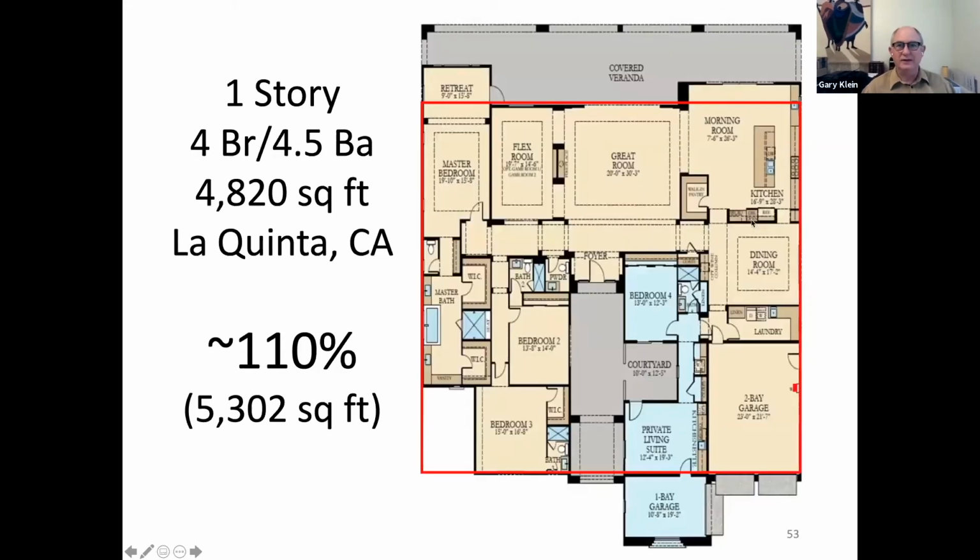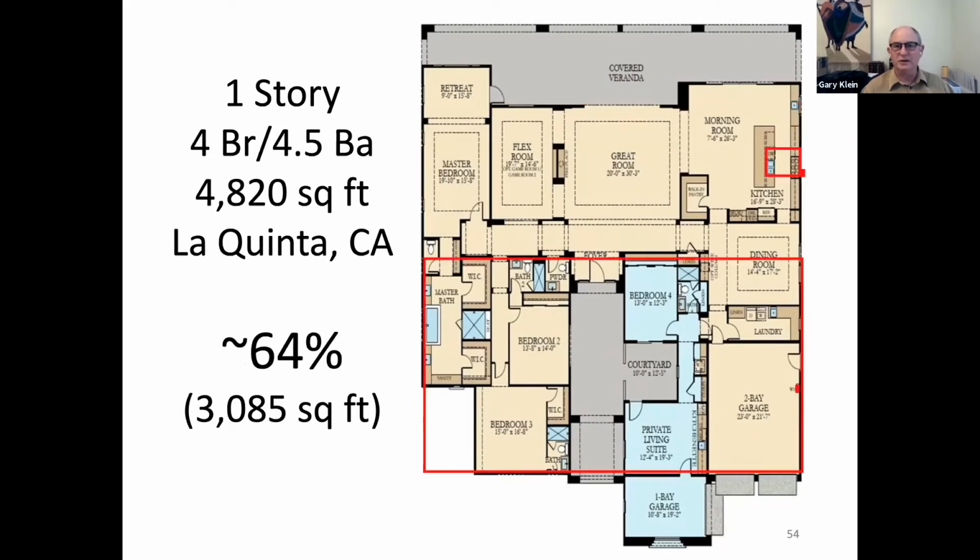How about this house? This one's, you know, a little pretty bad. It's got one water heater location in the garage. What if we split it and put a water heater just for the kitchen? That island sink in the kitchen is really hard to get plumbing to. It's way, way longer pipe than you think. It's over 25 extra feet of pipe to get there, right? Plus I had to start from here, right? I had to come from the water heater. So somewhere about this point begins my branch. That's almost a 50-foot run to that sink. And it's underground. So did you insulate it? I don't know. I don't know, right?